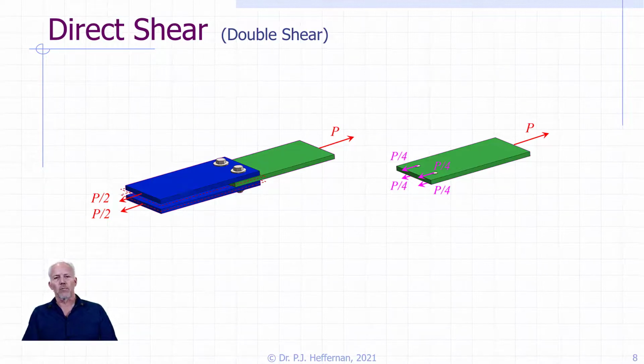This kind of demonstrates one other choice that you might have as a designer if you were designing a connection like this. We've talked about sizing the bolt, making sure it's large enough or strong enough, the right material to resist the shear forces. But you can also choose to make sure that there are enough of them. Can we increase the number of bolts? You have to have enough area in the joint in order to accommodate the bolts. But that's another choice that the designer has available to them when looking at shear connections, bolted shear connections.